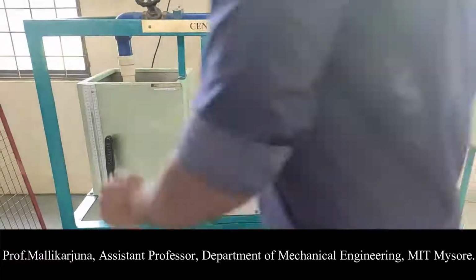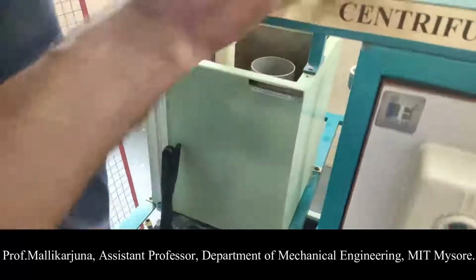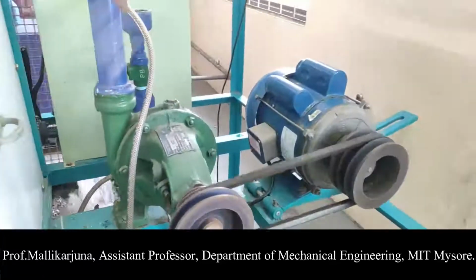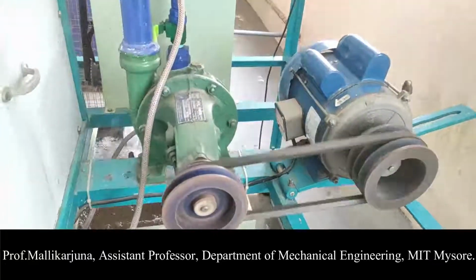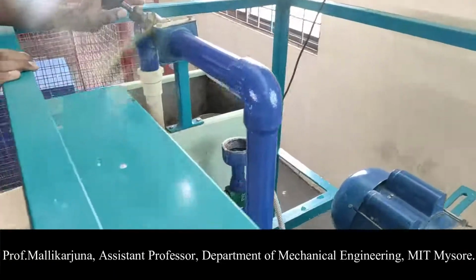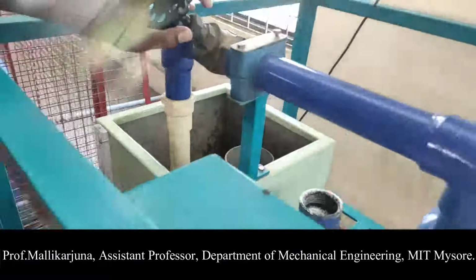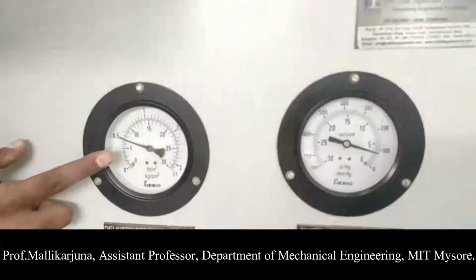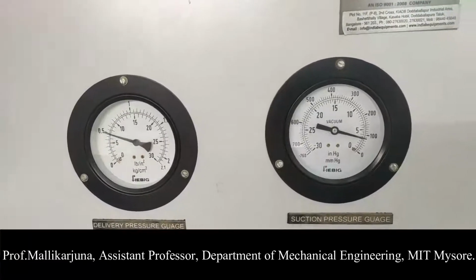Now the motor is supplying the energy. The motor is supplying the energy to the pump line. So now with the help of the delivery valve which we are provided with, please adjust the delivery pressure over here. So now the delivery pressure is 0.5. This has to be adjusted with the help of the delivery valve.